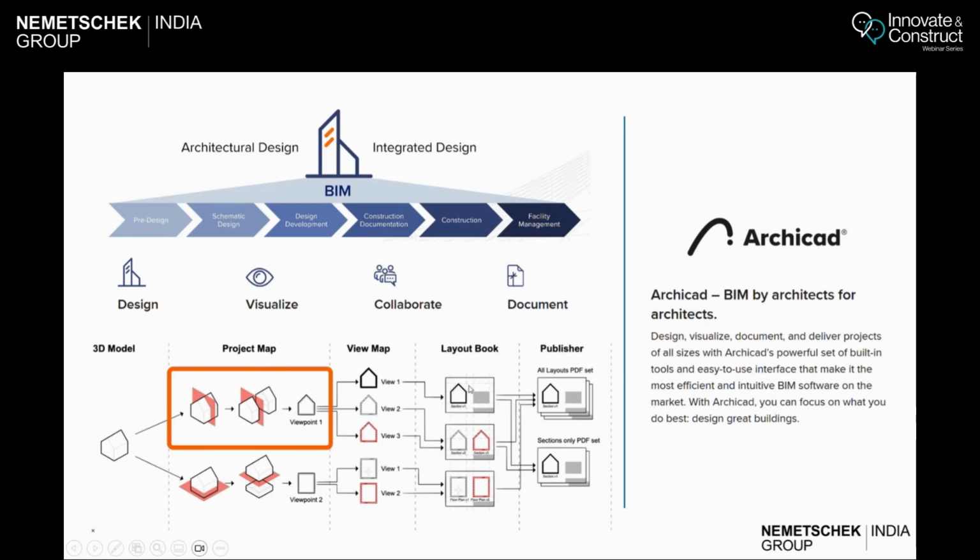design sheet. So all these design sheets as a bunch or a folder, I can create it and put it on a publisher. And this publisher set is what I export or publish from Archicad, which would be my final submission. So from the publisher, I can publish all my design sheets to PDFs, DWGs, and of course, BIMx format. So in this webinar, we will be talking about how I can publish my design documents to BIMx and what BIMx will let us do.